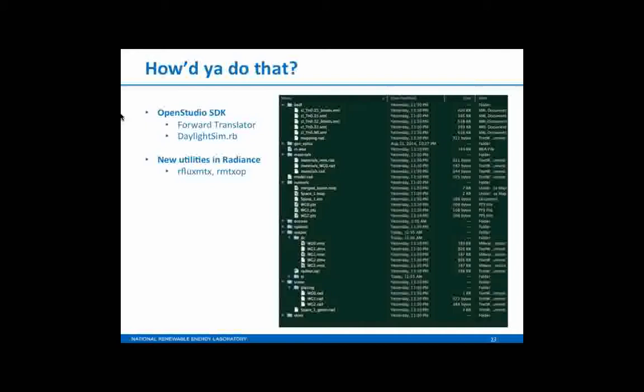It generated all this stuff, except in the case of the XML files, these are the BSDF windows. These are pulled from the building component library. They're generic. It just says the window is 25% clear glass. Go get from the BCL a BSDF for clear glass, 25% TVIS, and clear glass with Venetian blind.